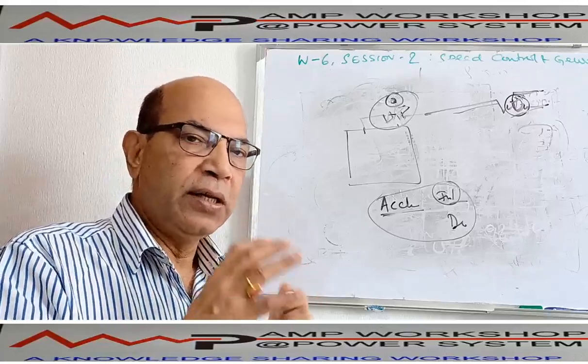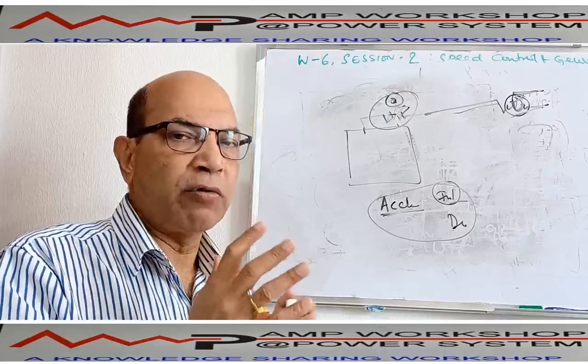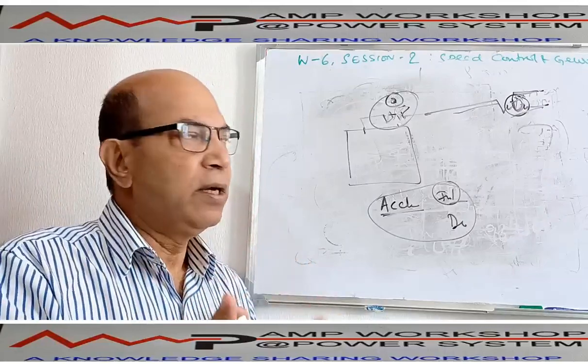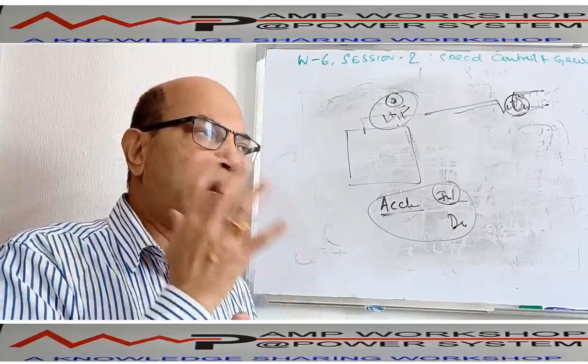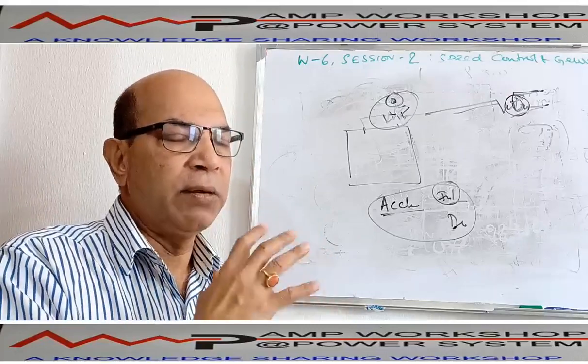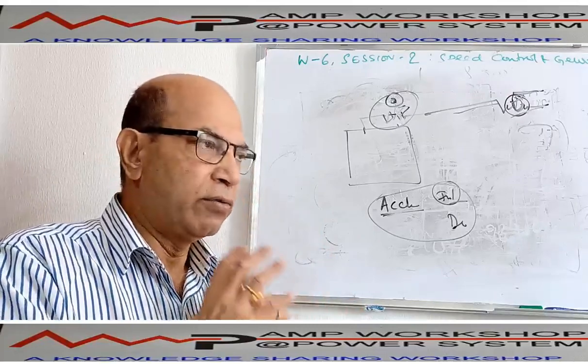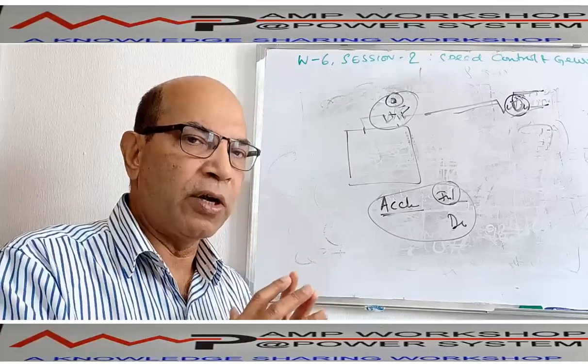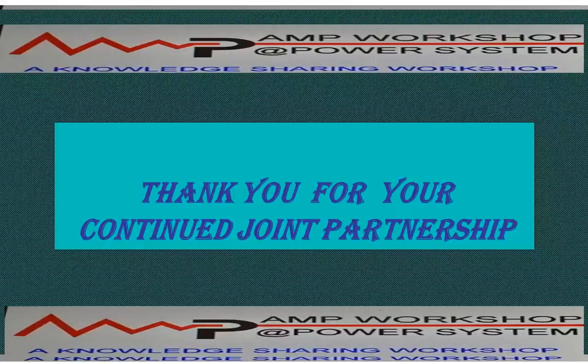As we have said, apparent power has two parts. One is the active part, another is the reactive part. The governor is used for the turbine's active part control, which is given by the turbine to the alternator. So you have to keep in mind, the governor is a speed controller, but it is actually controlling the output active power of an alternator or generator.